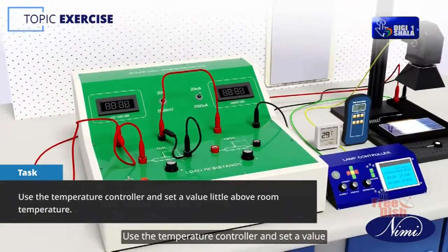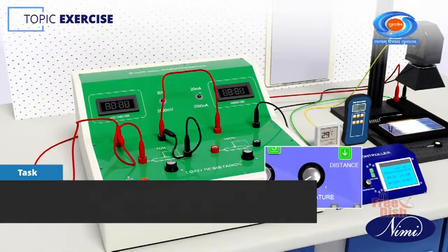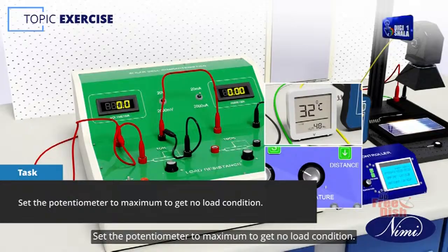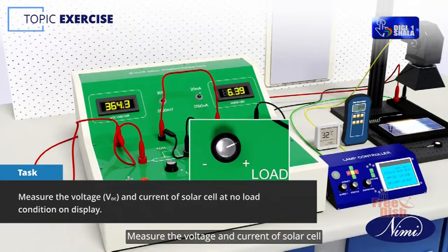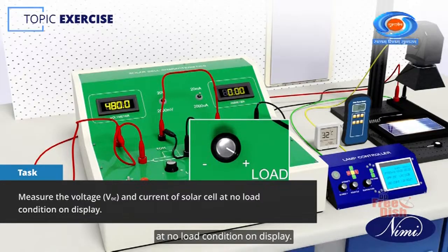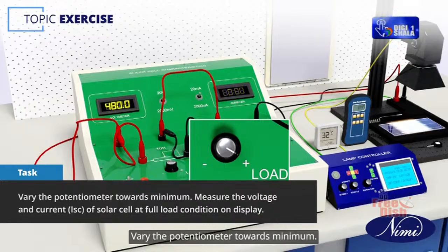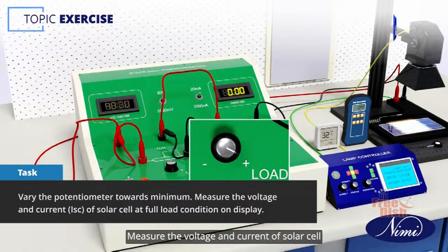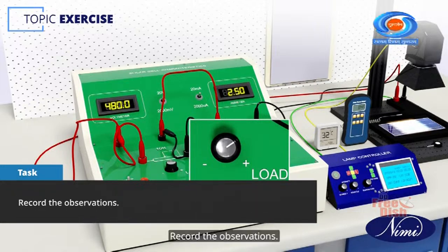Use the temperature controller and set a value little above room temperature. Set the potentiometer to maximum to get no load condition. Measure the voltage and current of solar cell at no load condition on display. Vary the potentiometer towards minimum. Measure the voltage and current of solar cell at full load condition on display. Record the observations.